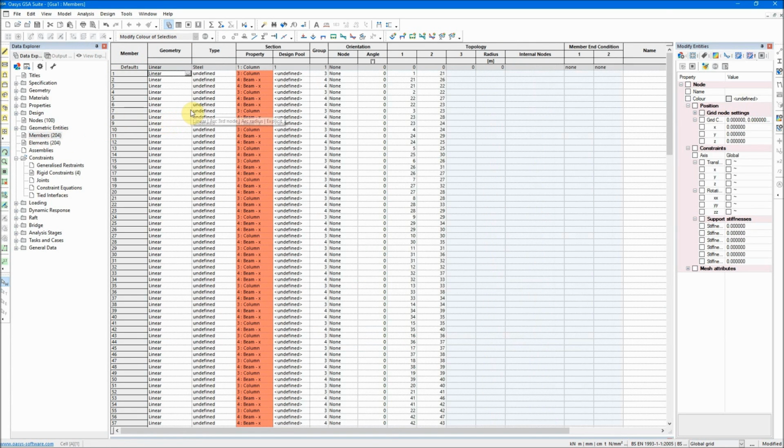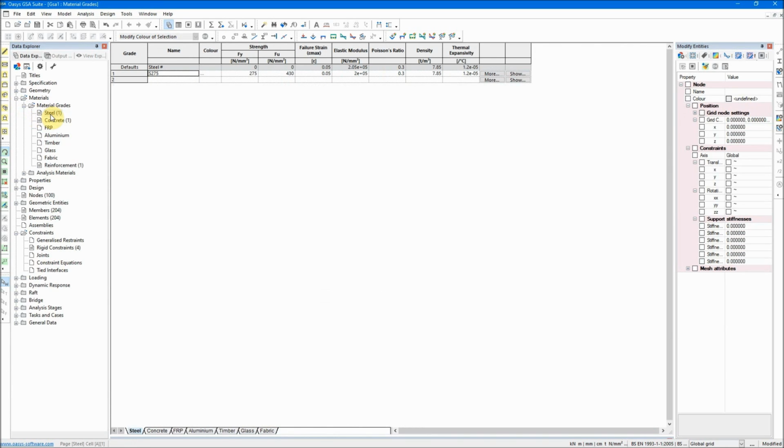And the members have been selected as well. In this case, the beams and the columns cross sections that I have defined are allocated to each of those elements that we have. As you can see, again, a node is indicated and the beams and columns are defined. You can see the material which have been defined here as well. So a steel material is defined, S275, and I only have defined one type of concrete, the C25/30. These have been all defined previously using the wizard. So the wizard helped us fill in these forms. Otherwise, you had to do this one by one.